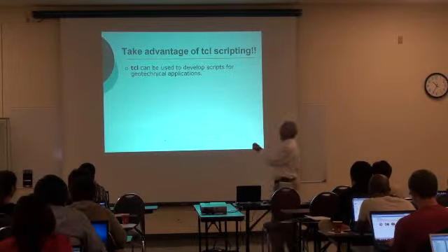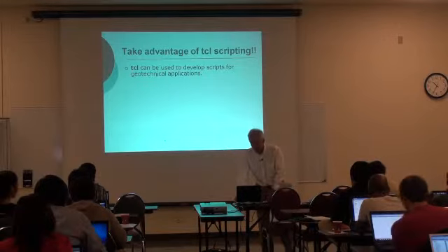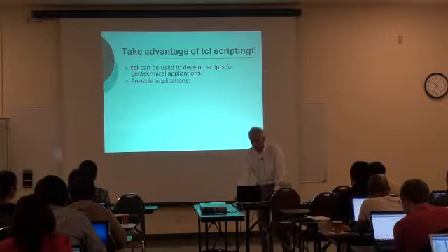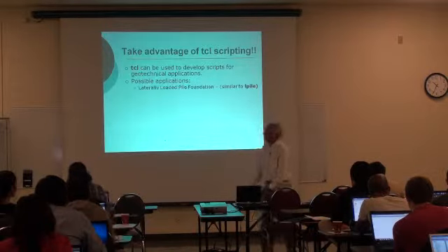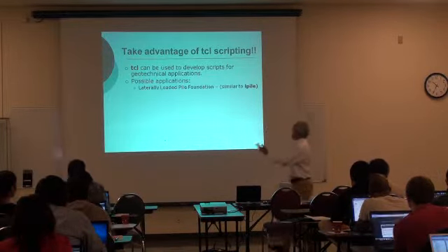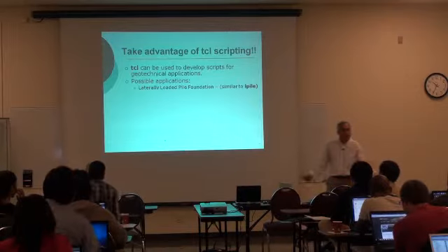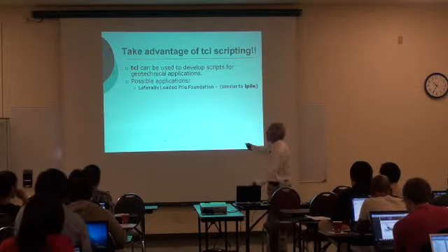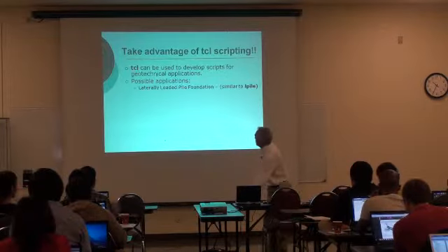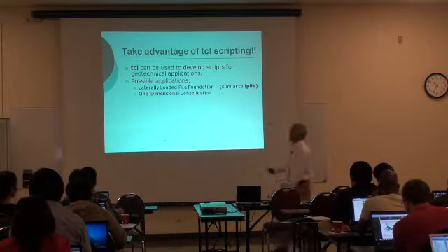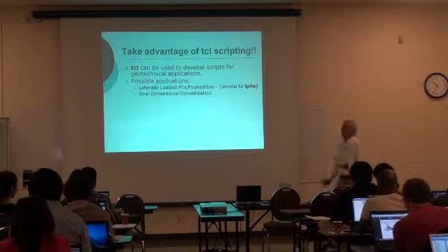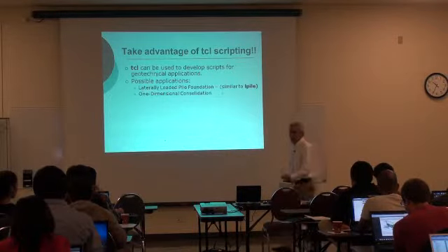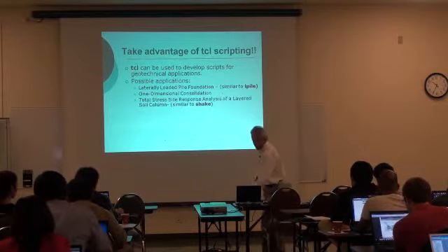So TCL is, as I mentioned, an excellent tool to develop scripts for geotechnical applications. And the applications that we can use are, for example, laterally loaded pile foundation. That's similar to LPile. LPile is a commercial tool that is available, so we could do the same using OpenSees. One-dimensional consolidation, a typical problem that we want to handle. Again, let's develop a little script that can be used for this.